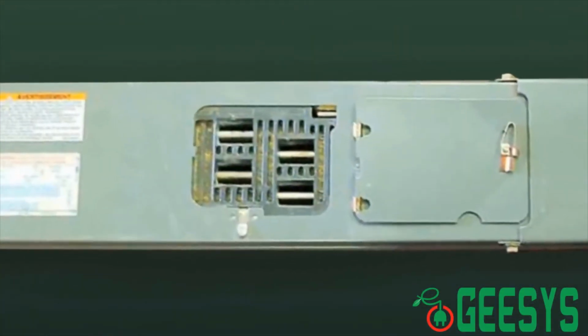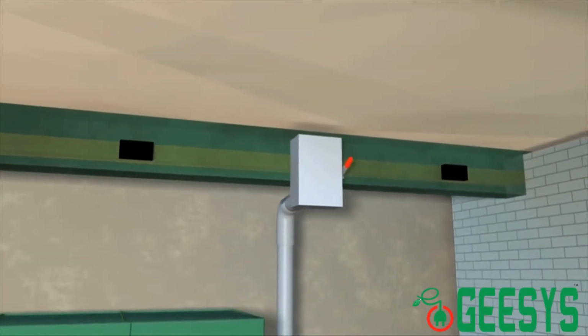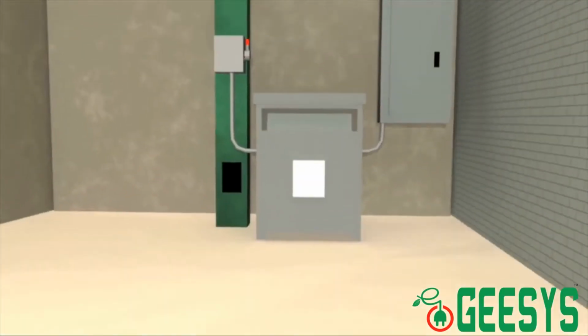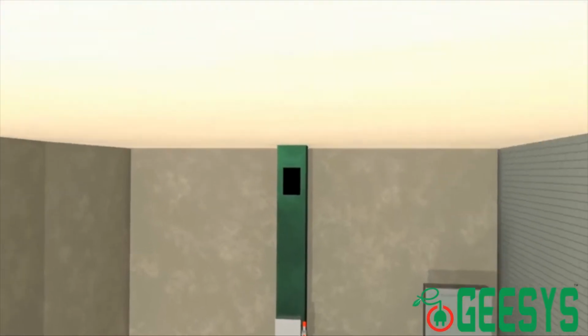Plugs or connectors are spaced every 2 or 3 feet for the purpose of attaching fused disconnect safety switches, which can then supply voltage to designated areas. In our example facility, you see the bus duct rising vertically to the roof. It passes through an electrical room on each floor.